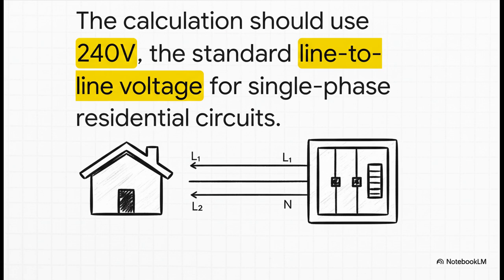We're talking about household cooking appliances. In a standard house or an individual apartment, the power for a big appliance like a range or an oven is going to come from a 120/240 volt single-phase 3-wire circuit. It's the most common setup there is. You get that 240 volts by connecting across the 2 main power lines.